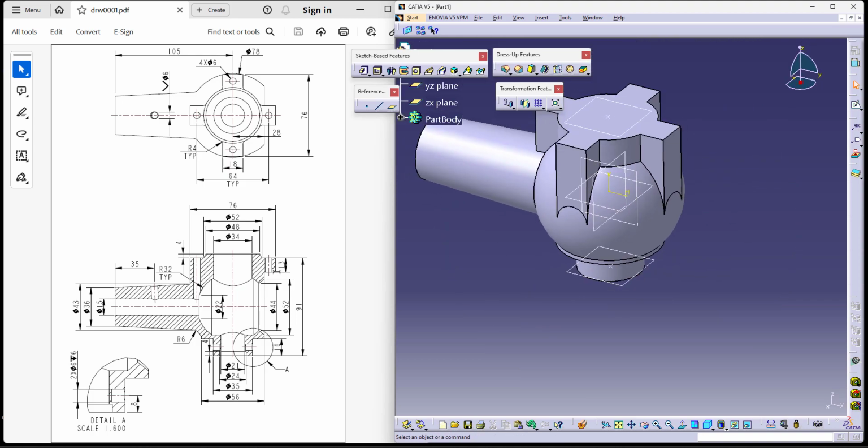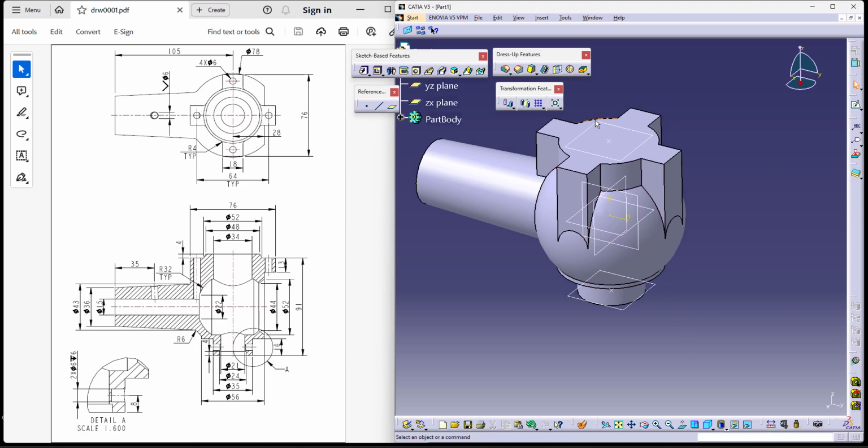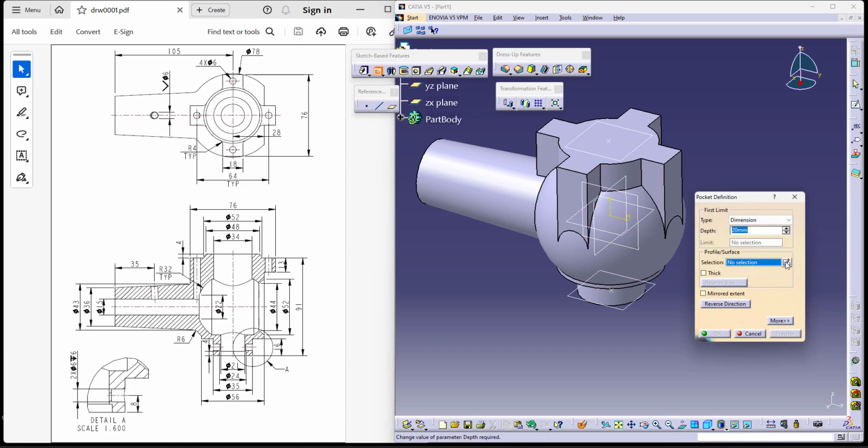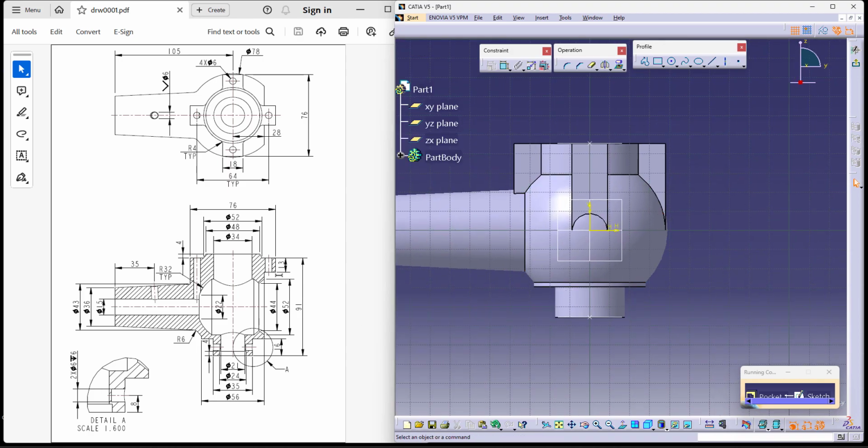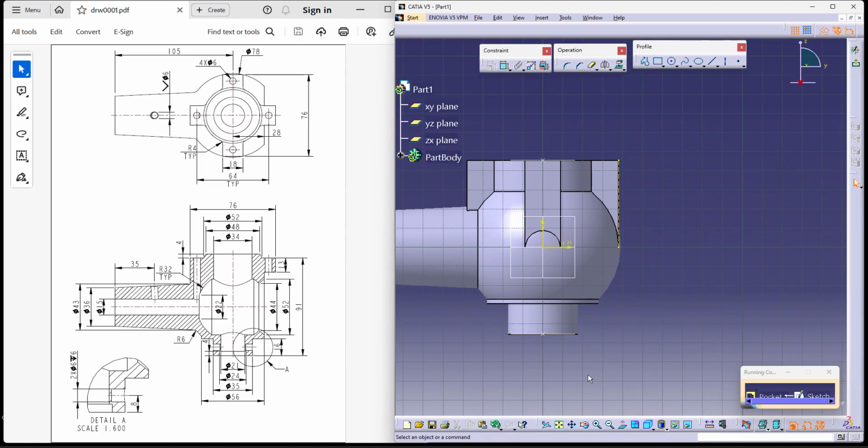After this cut, I do have another cut here which is actually in line with the 56 there and it's removing through the existing sphere. So I can directly use the pocket command to do so and just directly select the pocket and the front view and start removing the material. The material is actually removed from 13 from the top. So I'd be using this as my reference so I don't remove anything else. And then this is the last reference I have.